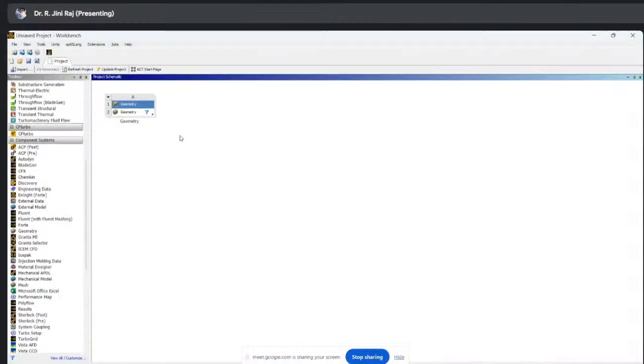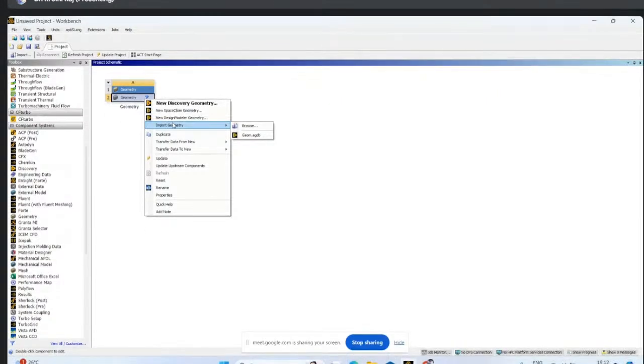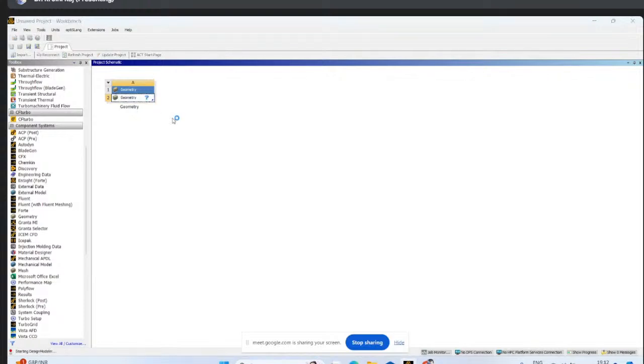So here what I'm doing is I'm just opening the geometry. I want to create a cylinder. Now our exercise is limited to 2D analysis. So what we are going to do is make one circle and make a control volume over that. Once that is done, we can see how to visualize the flow over a cylinder at a particular Reynolds number or a particular velocity through Ansys.